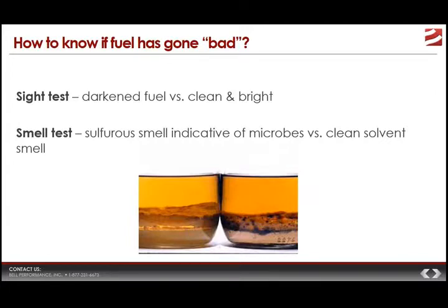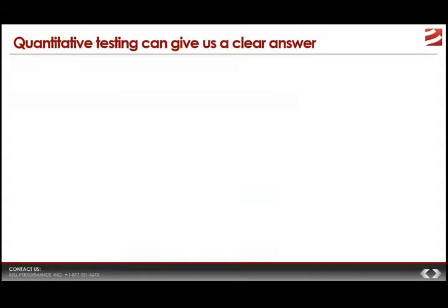Or does it have kind of a sulfurous smell? If it's got a sulfurous smell, then that's indicative of microbial activity. So these are pretty simple to do, but you would be surprised at the number of people who don't even think to do this simple thing. So sensory tests are good to use, but they're not the be-all and end-all, because a sensory test can only give you a generalized conclusion. Yeah, it looks good. Yeah, it looks bad.